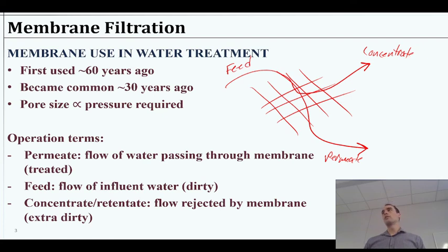And that is going to be a concentrated dirty water, right? So the mass balance here is we have some amount of mass of particles, contaminants, whatever we're dealing with, and some amount of water, neither of which is going to change in the system. It's just that we're changing the directions. It's a lot like when we mix two streams with different concentrations of something. They come together and make a final stream with the combined mass, except we're doing it in reverse, right? Since we have a separation process, we are taking one stream and splitting it into two different ones. This is like the one time where we can split a flow rate and have different concentrations on either side.